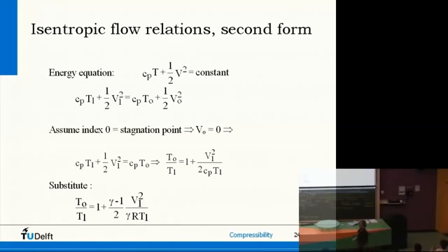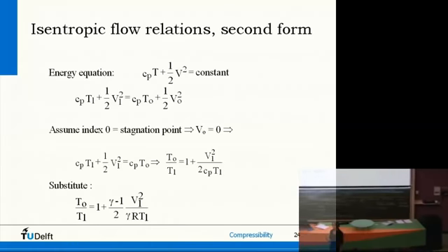That might be related to the speed of sound squared, right? A was square root of gamma RT. So A squared is gamma RT. I don't have the gamma and R yet, but suppose I have here also a constant. So suppose I can rework this gamma and R into this. Then this T can be A squared, and I have V squared over A squared, so Mach squared. So the only question is, what is here in front? How do I get from this CP to gamma R? So that's what I'm going to do on the blackboard. That's a few intermediate steps.